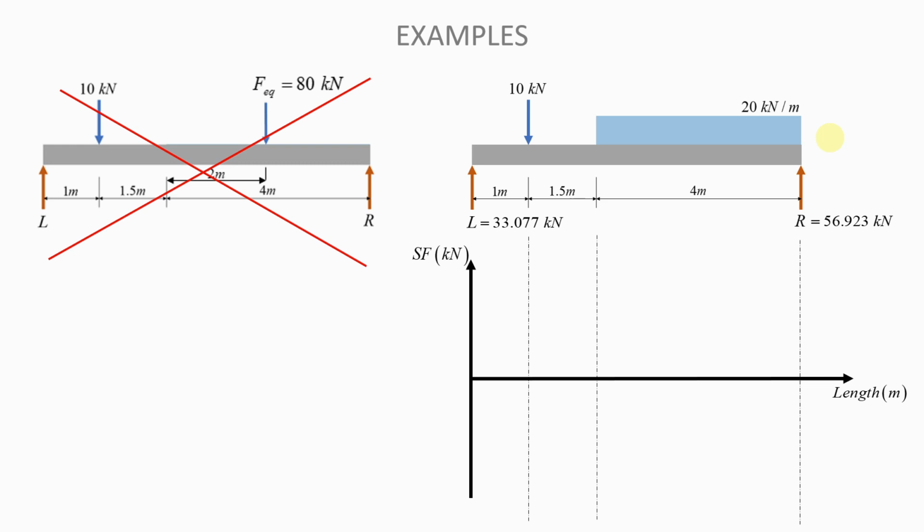Okay, that is basically what it is. But if we had a situation where maybe you have a point load in the middle of the UDL, then where you have that point load will also be a location of interest. But in this case, our UDL does not have a point load in the middle of it. So the location of interest when drawing the shear force diagram will just be the beginning of the UDL and the end of the UDL.